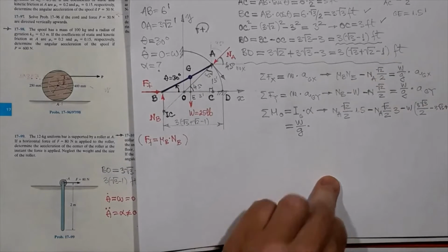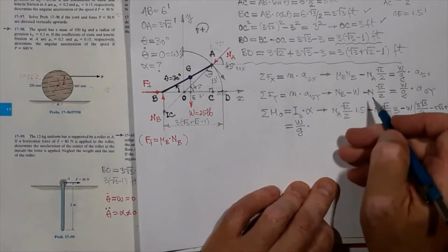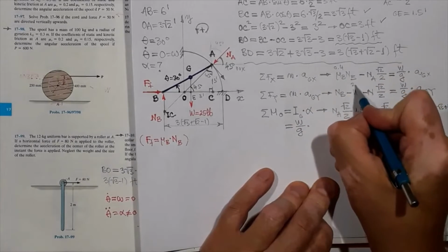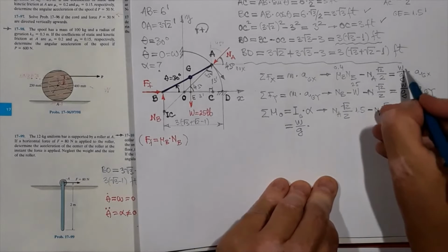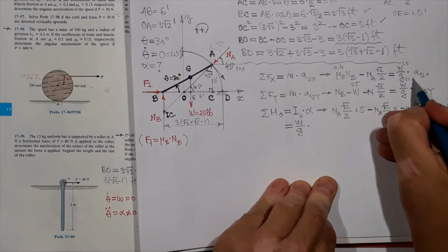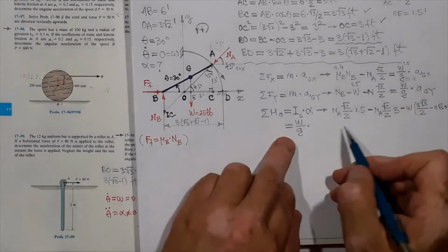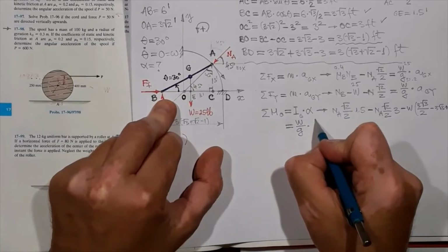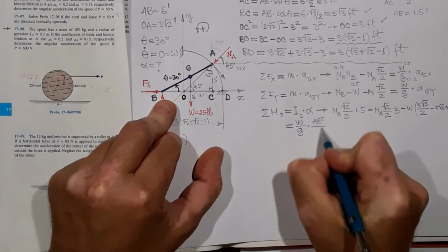Well, we'll need to go through these equations one more time and fill in everything that's known. So 0.4 will be here. This is 25 pounds, 25 over 32.2, okay. All right, so I said W over G times distance AB squared. That's right, AB squared over 12.